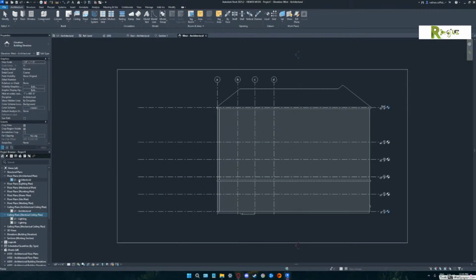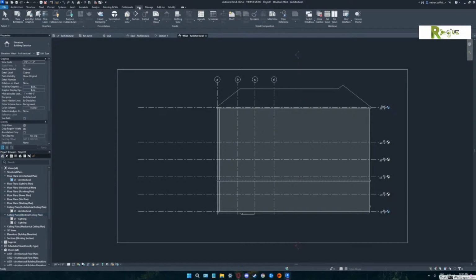Yeah. I want to show you how to add the missing ones, because you don't have L2, L3, L4, L5, and roof. So we're going to add those. If you go to the toolbars at the top, I need you to go to the one that says view, not that top, that one there, view. And right below that is the one that says plan views, a button. You're very close to it. Go a little bit to the right there. Say plan view, floor plan.